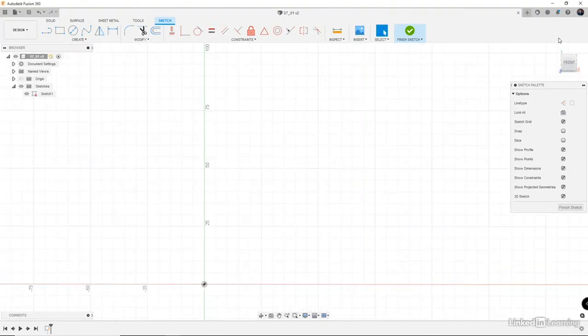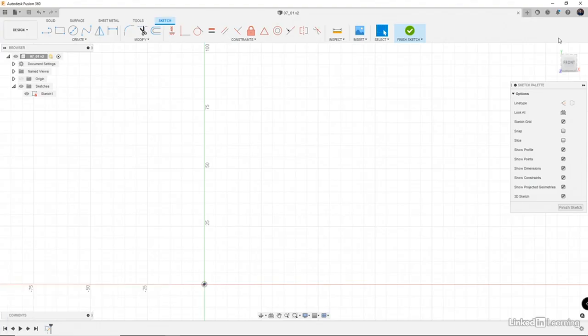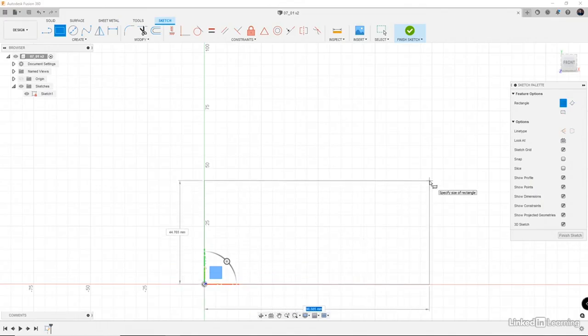Now let's go ahead and drive some 3D bodies from some sketches. So let's work on all the things that we've talked about with Sketch and build upon that so we can drive some 3D geometry. Let's go ahead and use the rectangle tool. Just hit R and we'll specify the origin here, which is fine. We'll go, let's say, 125 by 75 millimeters.